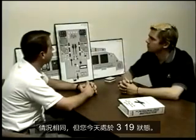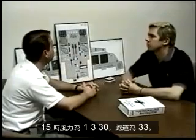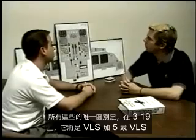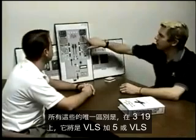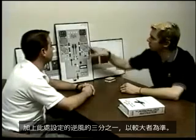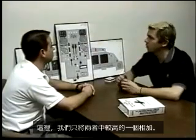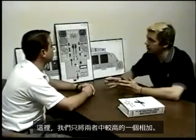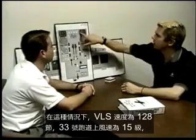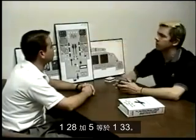Same scenario, but you're on a 319 today. VLS is still 128. Mag winds are 330 at 15 and runway 33. How's V approach calculated for the 319? Okay, the only difference in all of these is that on a 319, it'll be VLS plus 5 or VLS plus a third of the headwinds that's set in here, whichever is greater. On the 320, we added both. Here, we're only going to add the higher of the two. In this case, with a VLS of 128 knots, mag winds of 330 at 15 on runway 33, a third of those headwinds is 5 knots. 128 plus 5 is 133.